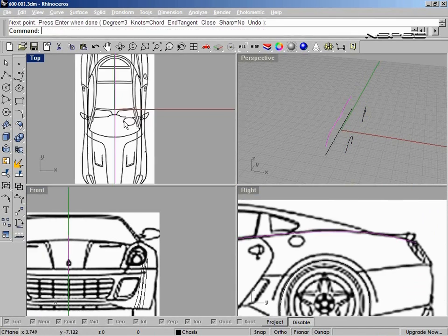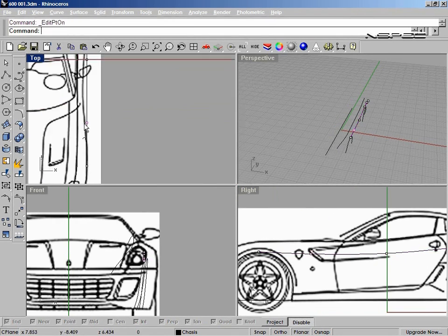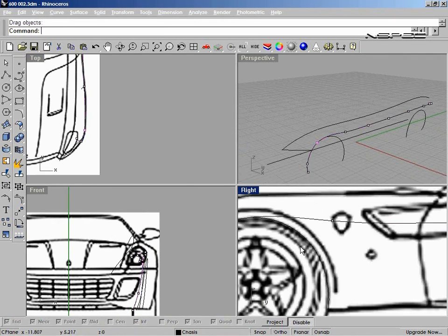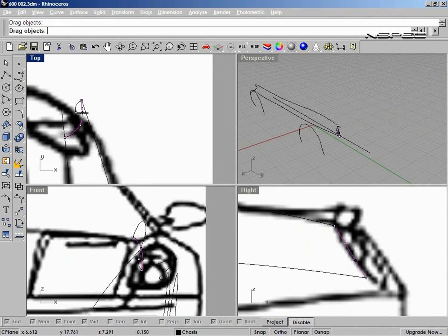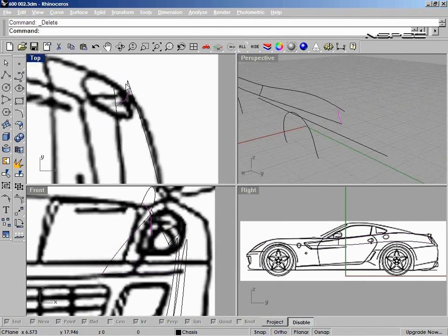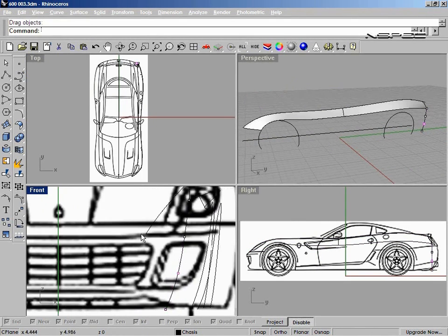Let's start off with some maneuvering basics. To pan, you would right click and move the mouse, and then you can move whatever view you're looking at, side to side or wherever you need to move it to. To zoom in, you would hold Control, right click and move the mouse, and that lets you zoom in or out.